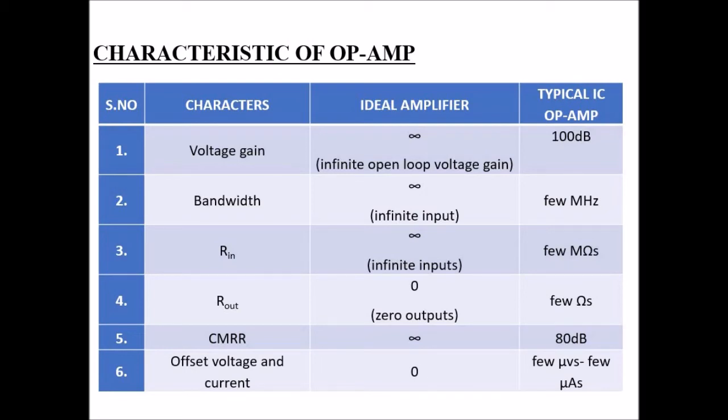Input resistance should be very high. We cannot make that 0. Why should it be maintained high? Only if it is maintained high will the leakage current not be diverted to some other minimum resistance loop.